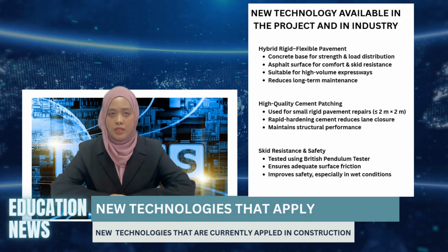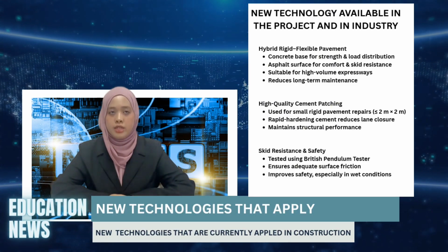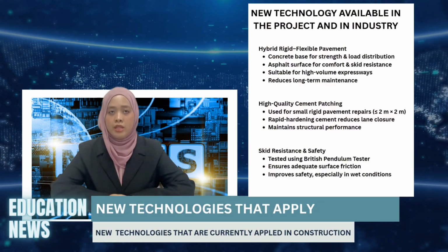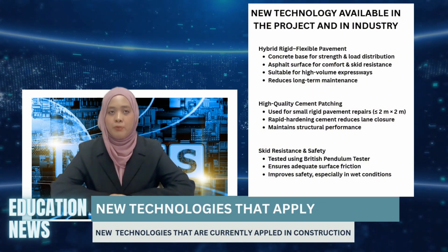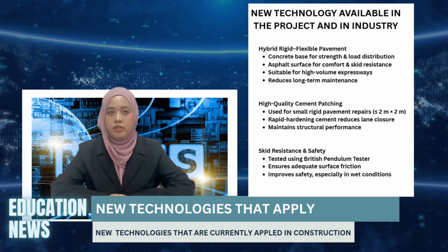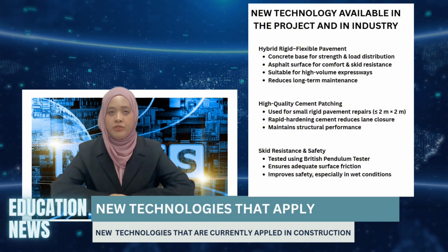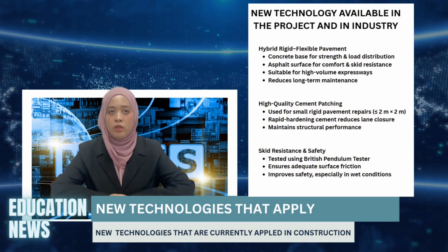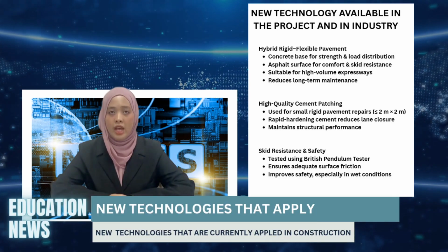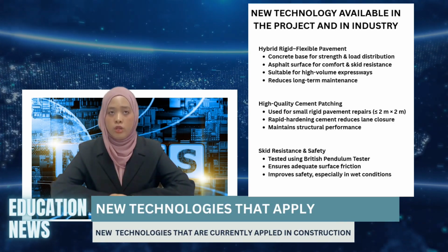In terms of safety, skid resistance plays a crucial role in modern road design and maintenance. Surface friction is tested using the British pendulum tester to ensure compliance with safety standards. Elevated skid resistance significantly improves vehicle control, especially in wet weather conditions, helping to reduce accidents and enhance overall road user safety.